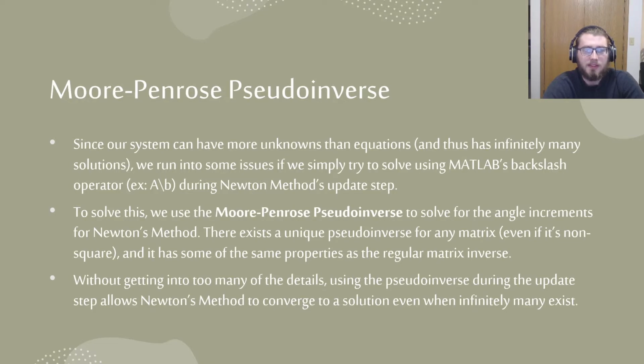And whenever we use this pseudo-inverse to solve for the angle increment during the update step, it does allow Newton's method to converge, whereas it did not with just MATLAB's default backslash operator for solving the linear system during the update step.